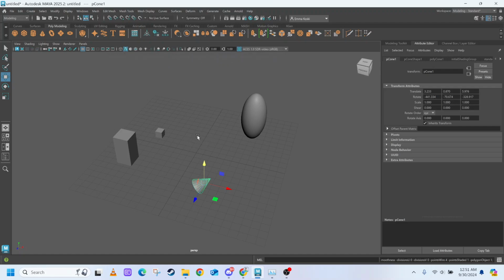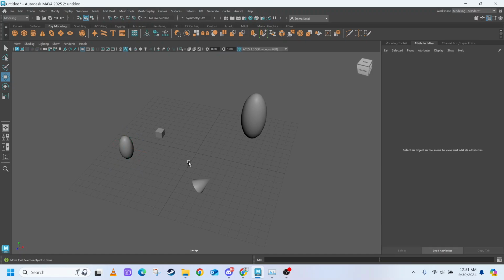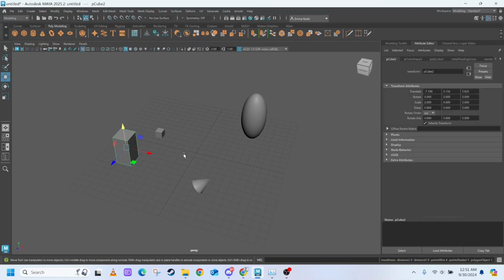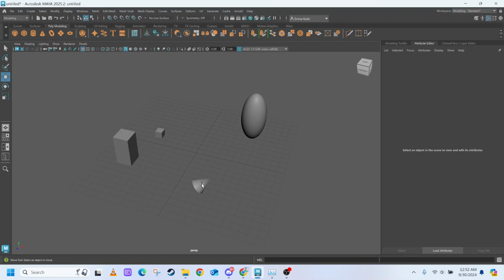And then the other thing I just clicked on is 1, 2, and 3 on your keyboard. Those will show you what happens if your object is smooth. Okay, so 1 is the normal mode, but if you click on 2, you kind of see this like transition mode of what will happen if you smooth your object. 3 is your object entirely smooth. Most of the time we're going to be using 1, but occasionally it makes sense to use 3.